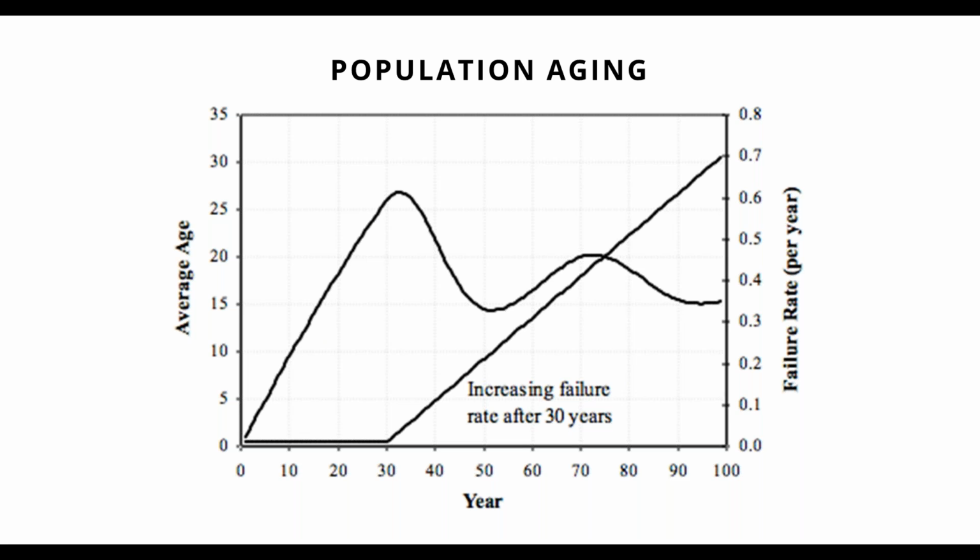But as failure rates start to increase at age 30, you see you're replacing old cable with new cable, and your population age actually self-rejuvenates. So, to a certain extent, aging infrastructure is a self-correcting phenomenon. The question, though, is just how many failures are you willing to tolerate on your system for various reasons. This is average age. When you're looking at aging infrastructure, oftentimes you don't want to look at average age. You want to know what percentage of really old stuff we have.